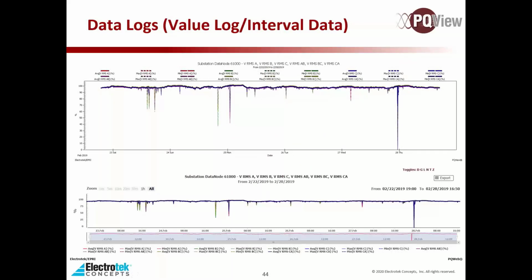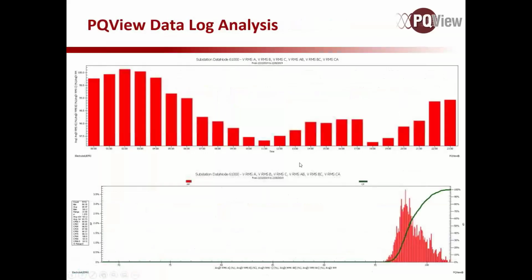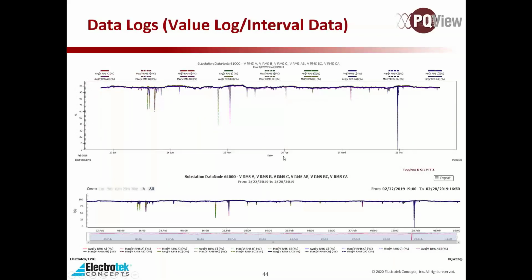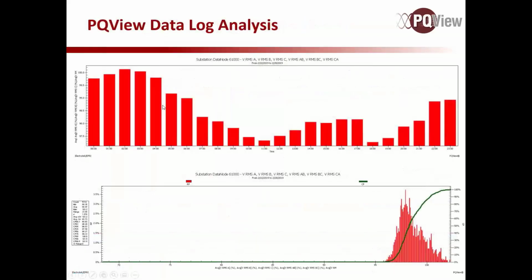We do also, of course, support viewing data logs, whether you call them value logs or interval data, all the same thing, but we call them data logs inside of PQView. Looking at this is the RMS voltage over the time frame. This is our static chart here, and this is our interactive one down below. You can zoom in on it, turn channels off and on, and export it, all that good stuff. We also have our analysis tools for data logs as well.